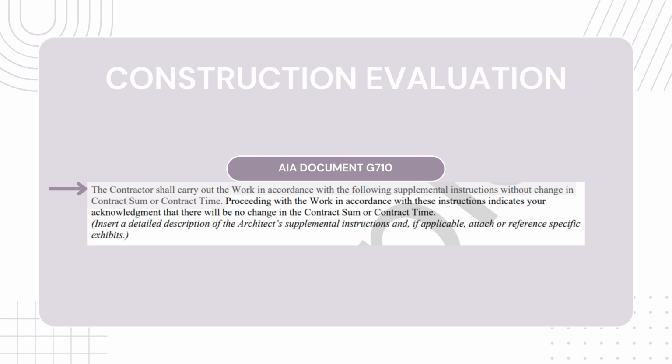A change order allows variations to be made to the original contract documents regarding the price, time, or both. They are issued by the owner since the contractor is under contract with the owner, but it is prepared by the architect. The change order must be approved by the owner, architect, and contractor.